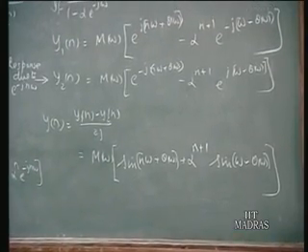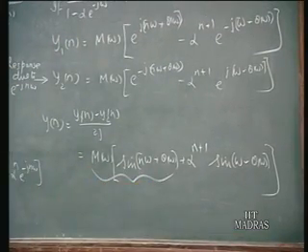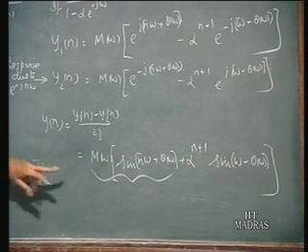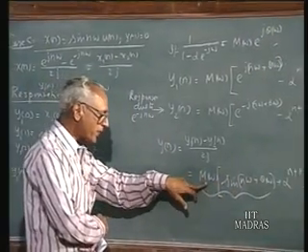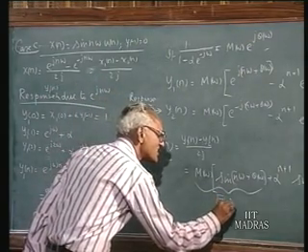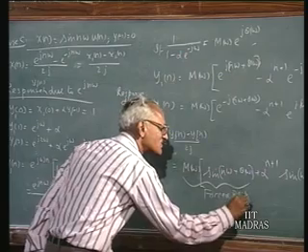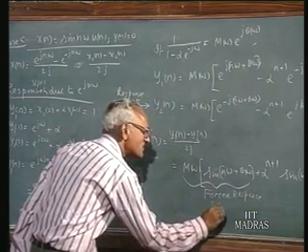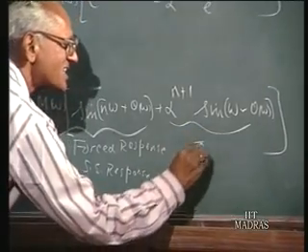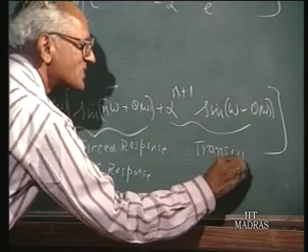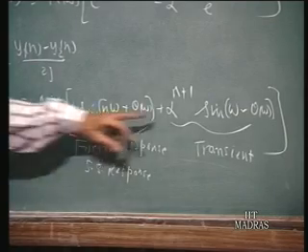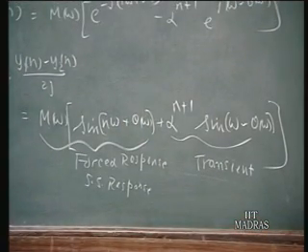You observe here that this is a factor which does not decay with time. You are driving this with a sinusoidal function sin nω, and the output also is a sinusoidal function sin nω modified in magnitude by M(ω) and by phase θ(ω). So, this is the forced response or steady state response. Whereas, this portion is a transient response, which comes from the complementary solution. And when n becomes very large, if α has a magnitude less than 1, this decays with time.